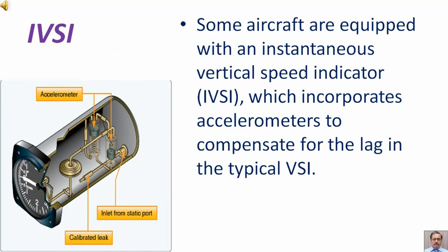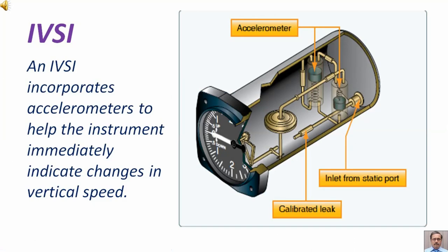Some aircraft are equipped with an instantaneous vertical speed indicator (IVSI), which incorporates accelerometers to compensate for the lag in the typical VSI. An IVSI incorporates accelerometers to help the instrument immediately indicate change in vertical speed.